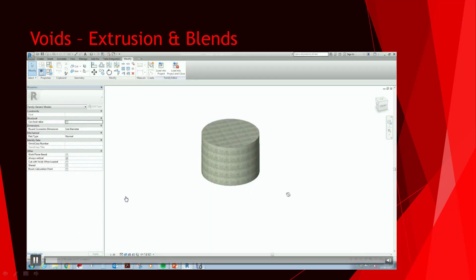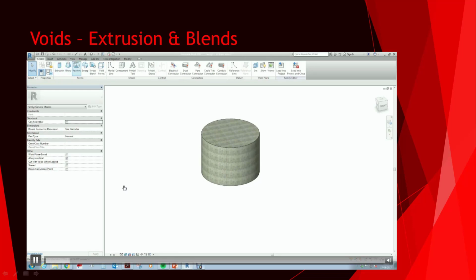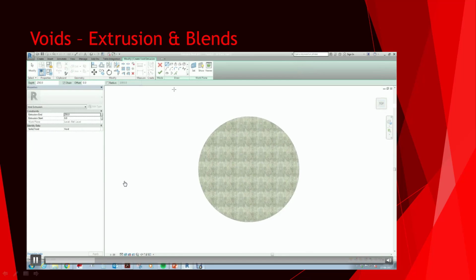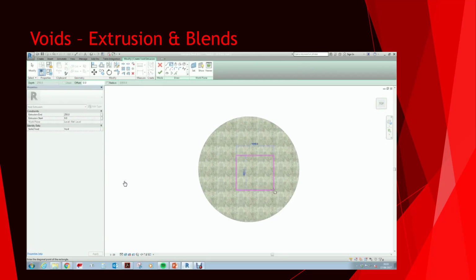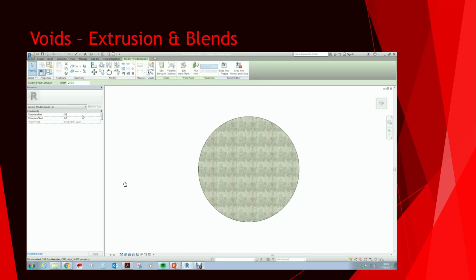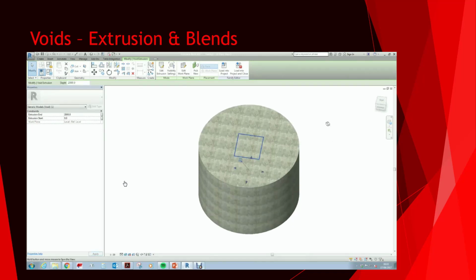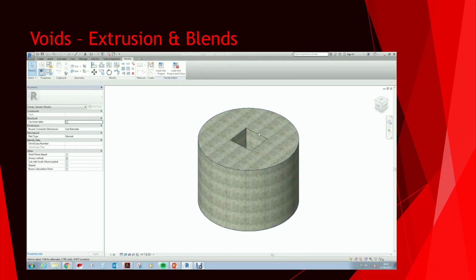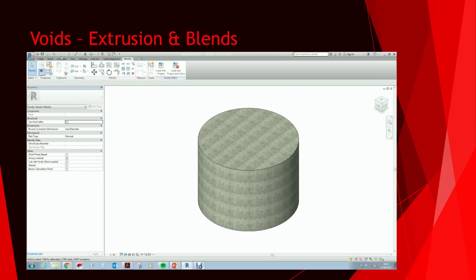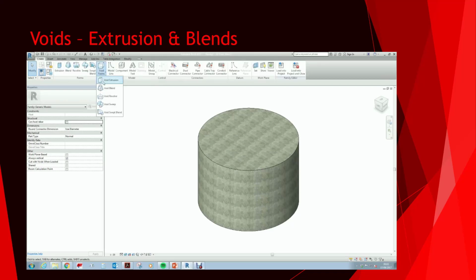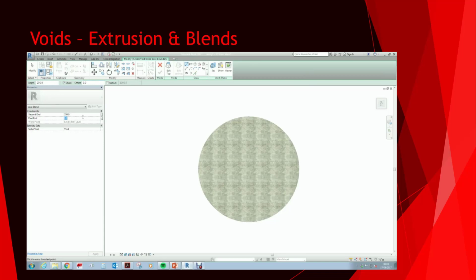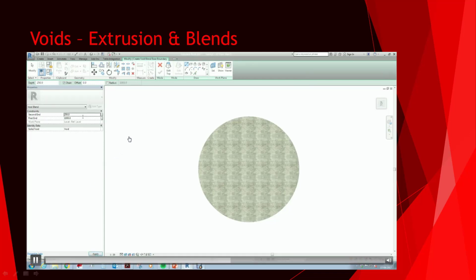So just a quick run through with these ones, same as before. You've got a void extrusion, so that'll be a basic profile, and it's going to get pulled across the level that you've stated in, or the extents that you want stated. So for us, like I've done a bit of water work myself. When you're branching across, that's handy when you're creating culverts, having the hole go down the center of it, and then you can start working on the inside of that, the walling of the culvert at that point, or manhole.